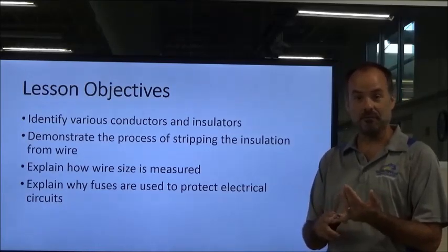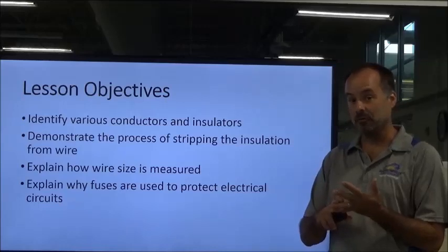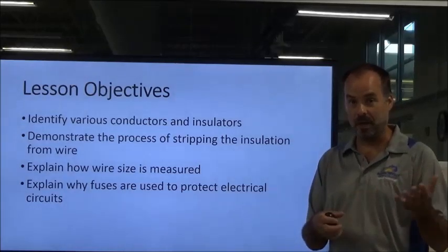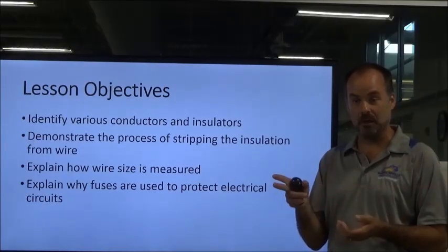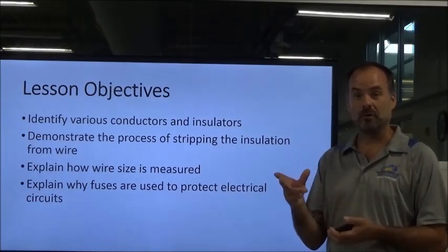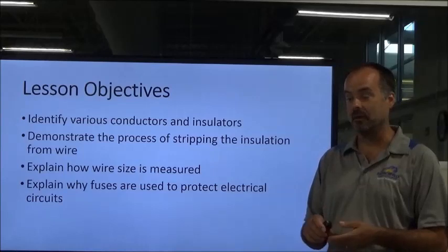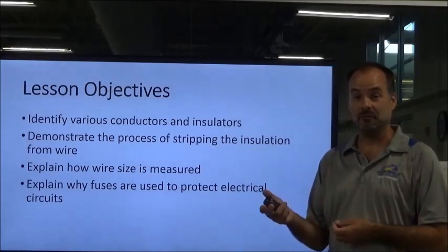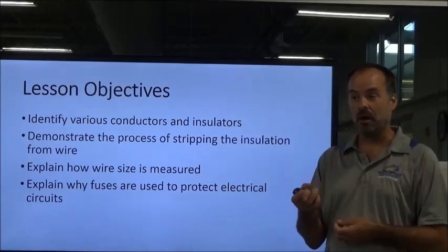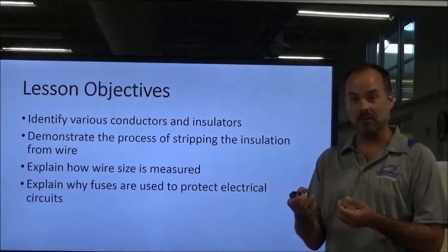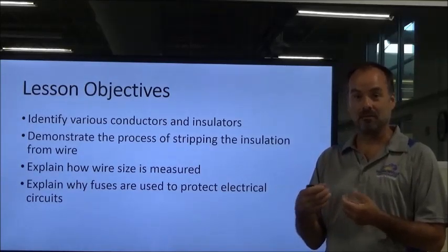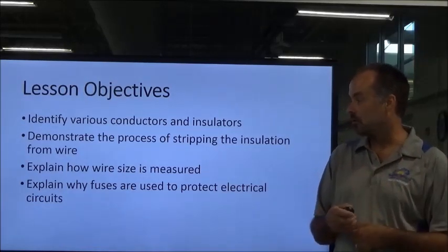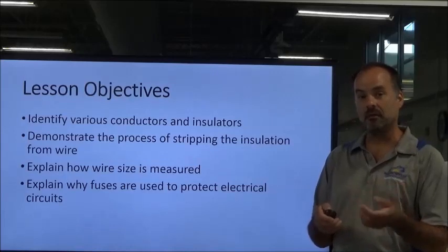One, like I said, for preventing fires. It also can be used to protect the equipment. If something happens, if there's a surge in power or something, that fuse could blow and open the circuit and protect the equipment that's after the fuse. If you have a high current situation, if there were no fuse, a wire or conductor would actually get hot enough to melt the insulation, which could also create a fire. So, like I said, you're going to learn more about fuses in the text.